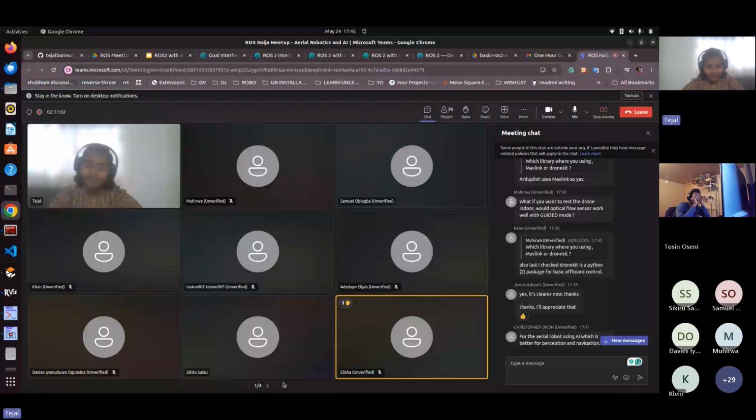The other way my company handles this is we have created a Docker environment where the Docker image is configured for one particular drone, and that configuration is very reproducible. We run each of those Docker images as a separate computer entity, so we just run the Docker compose YAML file, and it runs the entire 4 drones we want to simulate at the same time.